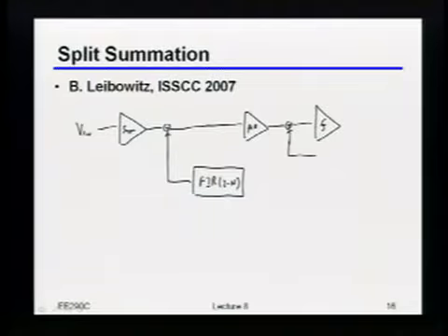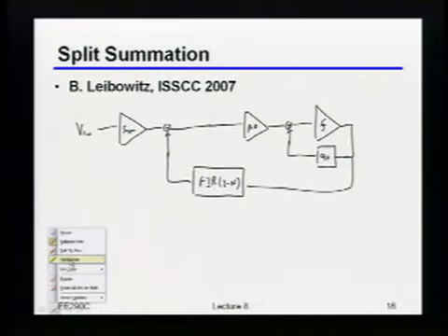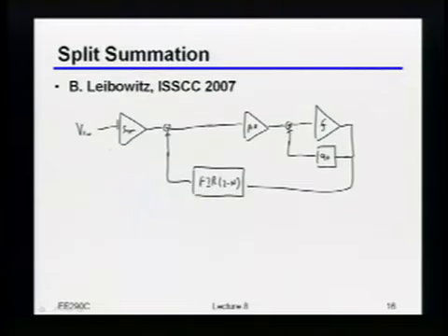So what I may basically do is, and let's just say that my first tap value, let me just call it A0, okay? What you basically do here is you just split it so that most of the work of the DFE, meaning most of the cancellation, is done in this first summation path. But just for that very first tap, you cancel it directly inside of this preamp loop here.